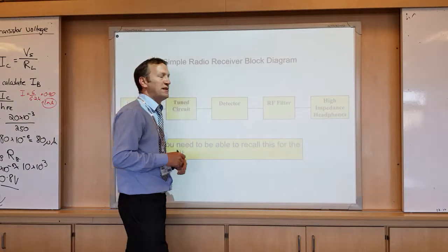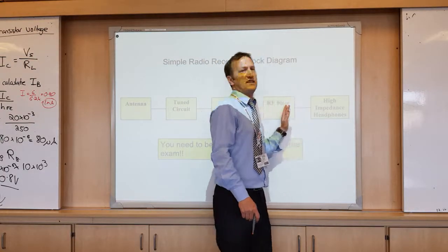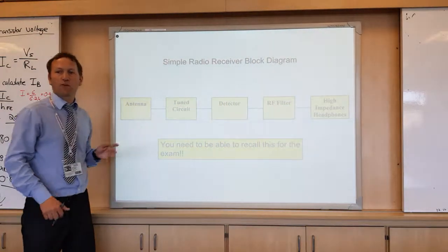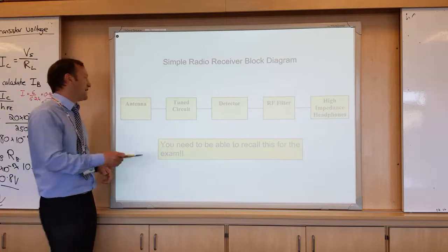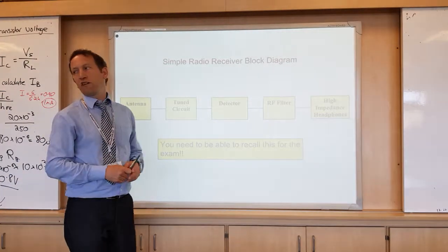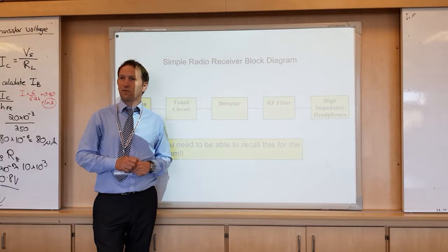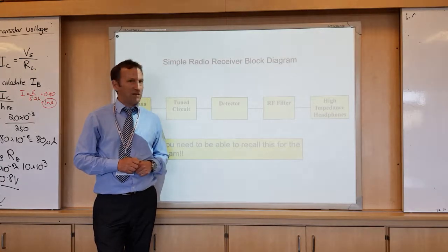They have to be high impedance because we don't want to load the rest of the circuit and draw current from it, because it has no power supply. It's getting its entire energy from the radio waves itself. Okay, so therefore we have no amplifier.